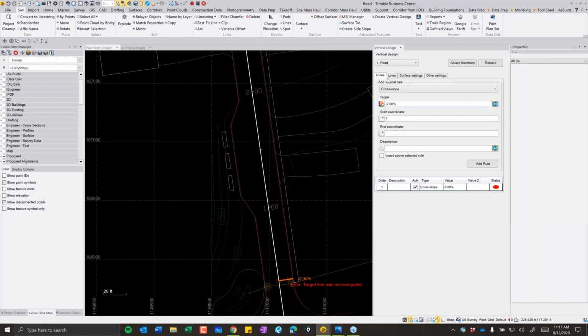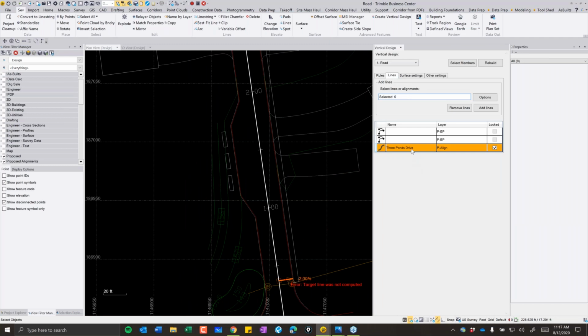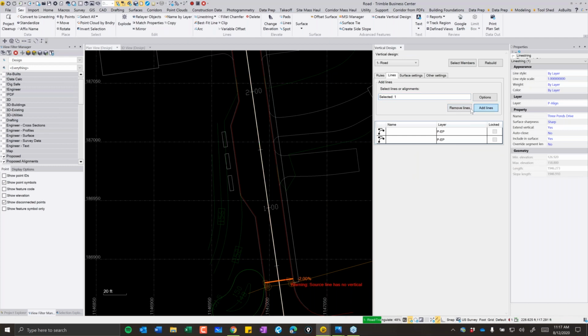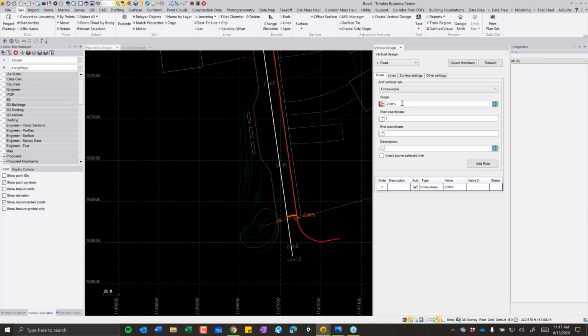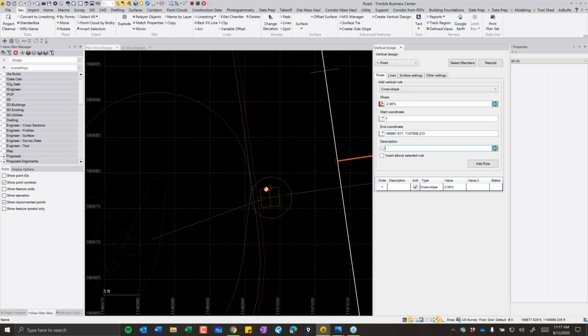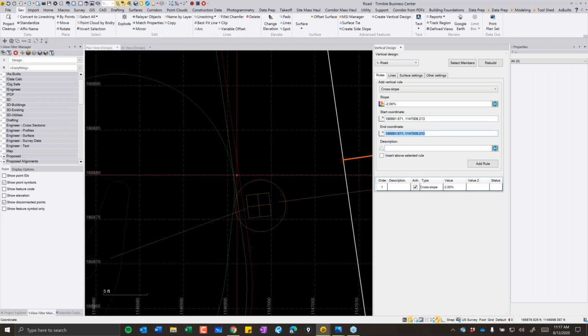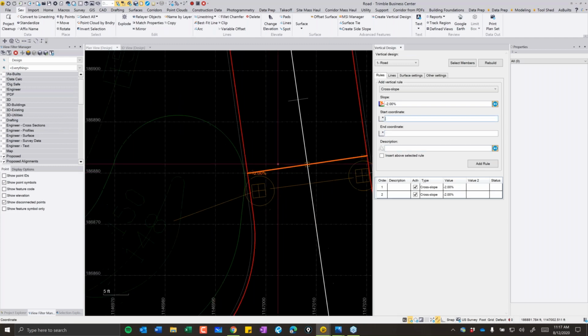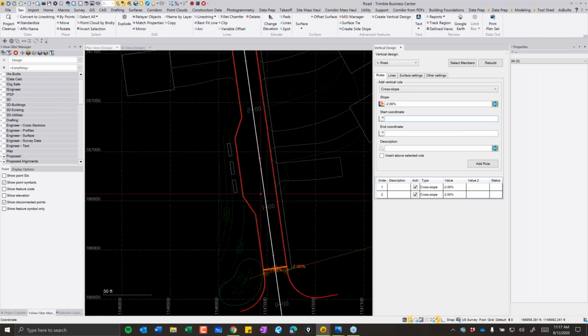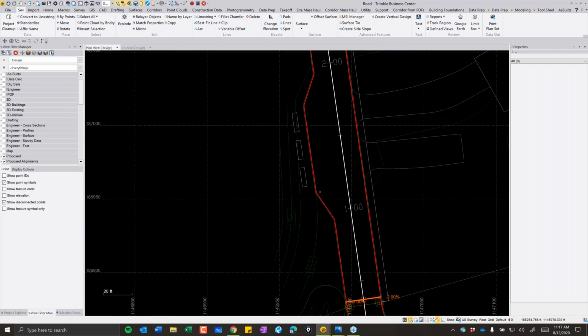Yeah, the challenge with this is that if the alignment, horizontal and vertical, aren't exactly the same length, it can throw an error in here. So using a line string and then cropping them so that they're the same length makes this work better, typically. So now by doing that, again, I'm just going to go from here, and I'm going to assume our cross section is 2% all the way for this example. Okay, now, so those are working now, right?